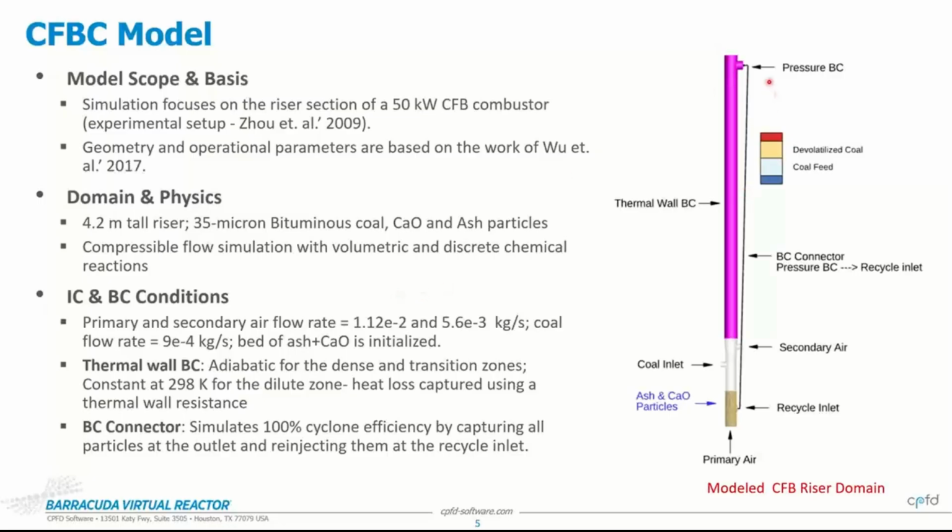Now, in the experiment, it was measured that the hydrocyclone is almost 100% efficient. So therefore, they do not include the hydrocyclone in the modeling, neither do we. But the nice feature of our software is this boundary condition called the BC connector. It stands for boundary condition connector. In this particular case, I'm connecting the pressure boundary condition with the recycle inlet down here.